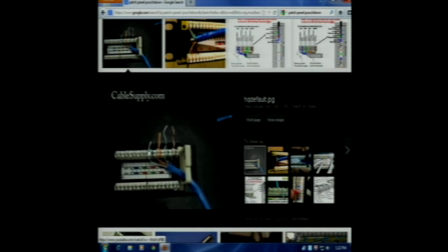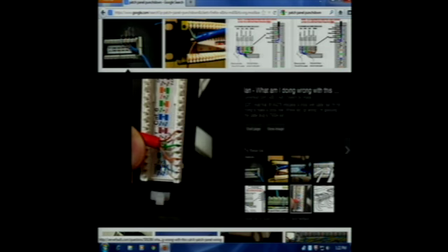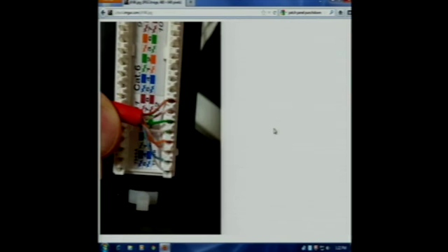And so you can see you have to drape the wire over, and it does have A and B, you're right. It's either here, or it will be like this one. Oh, no, that's the same way. So you can see there, hopefully. You guys see that okay? Maybe better rotate it. So each wire gets flopped over, and then you have this tool that you push it down, and inside here there's two little blades. Then if you go to the front side, so that's the punch down. That's called a punch down. You use a punch down tool to push them on. I just thought I showed you that.